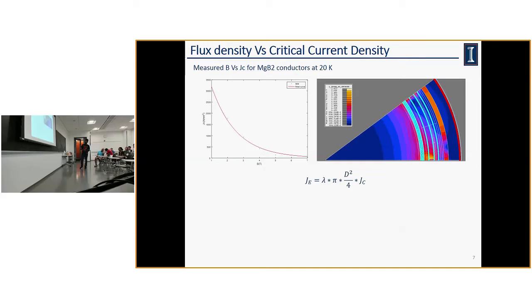So what I do is check all these conductors, the critical places, to see what the field is, and I always guarantee that I am below the margin when pushing current. For example, if I am operating my AC at 20 Kelvin and my field is 2 Tesla, I can go up to 200 amperes per millimeter square. But if the field is increased to 3 Tesla, then I can only push 113 amperes per millimeter square. I can't push more, because of this superconducting property.